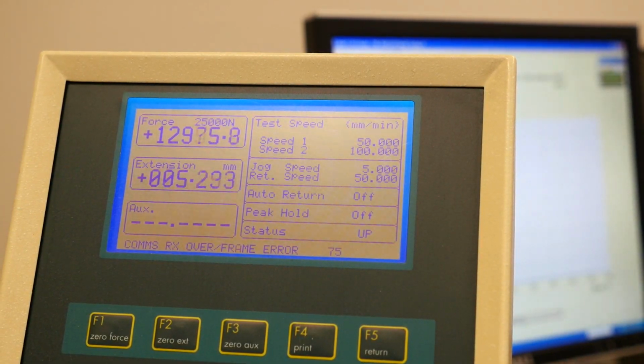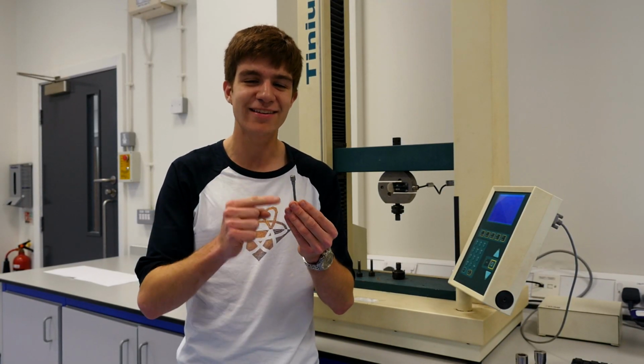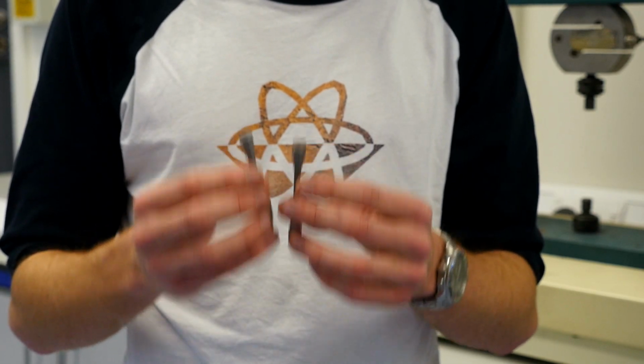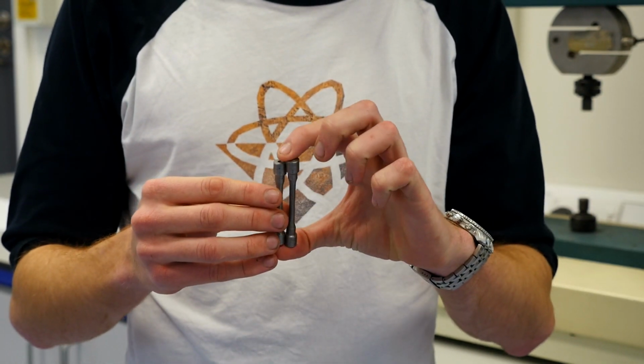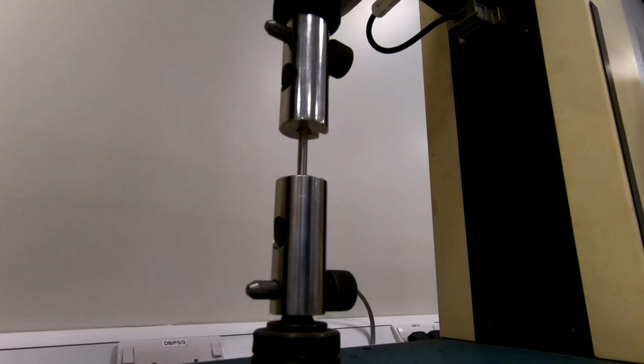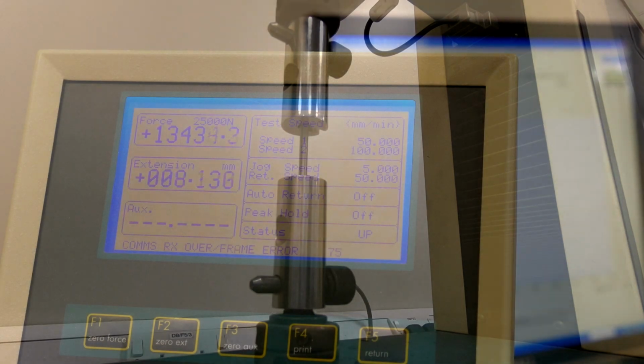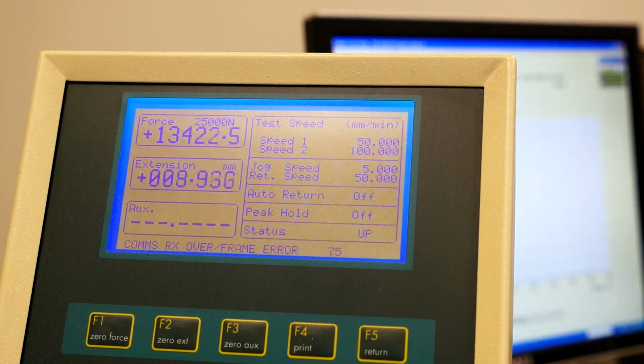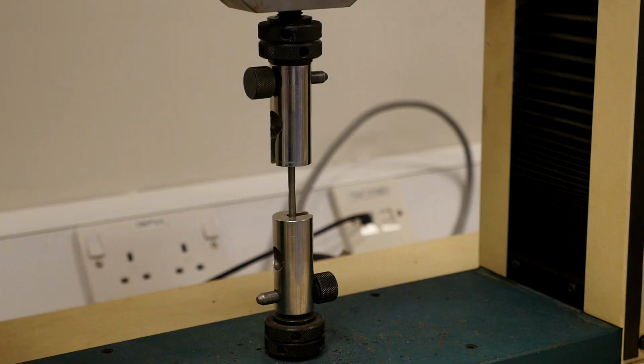If we add in enough tension, then this stretch stays put. It's undergone something called plastic deformation. As you can see by comparing it to an unstretched sample, it's become much longer. You don't really want this for things like elevator cables, but take note. If you did this with the bones in your leg, then you would actually get taller. Before you go running off to find your nearest Tinius Olsen machine to add a few extra centimeters of height, be careful of what happens at the next stage, when we add in even more tension.